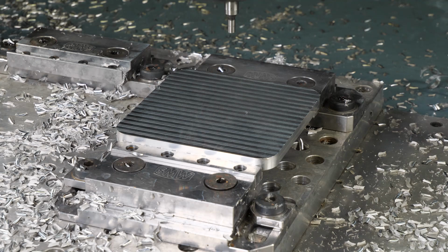Okay, so before I start this up, one thing to keep in mind with edge finders is they have a range of RPMs that you can spin them at. I like to spin mine around 1000 RPM, 1200 RPM, just to keep it in a safe limit, because if you exceed the listed limit on an edge finder, that wobbling tip at the end can actually break. It can become warped, and you might break your edge finder if you spin it too fast. So always double check that you're spinning at a good, slower RPM when you're running your edge finder.